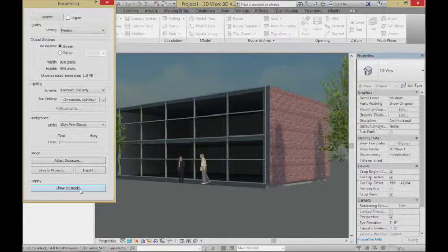If you have an imbalance, either we have too much air in the room and we're not taking enough away, we're infiltrating out, blowing out through all the cracks because all that pressure has to be relieved. If you are pulling away more air than you're introducing to the room, then you're infiltrating in, and all the air's coming in from the cracks under the doors and around the windows. Either of those is not a great situation. You like to keep it in balance, because if it's all infiltrating through the cracks, you're not really controlling it very nicely. You'd like to control all that in a very engineered way.